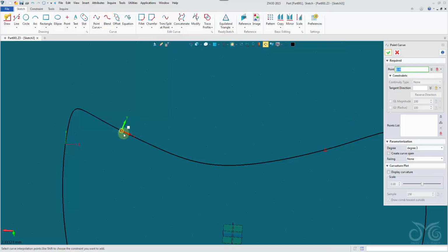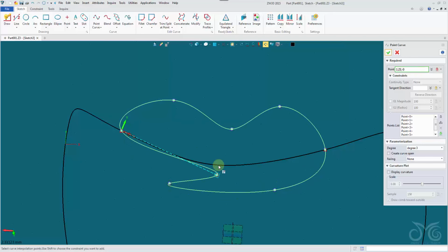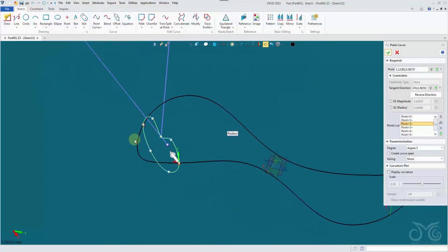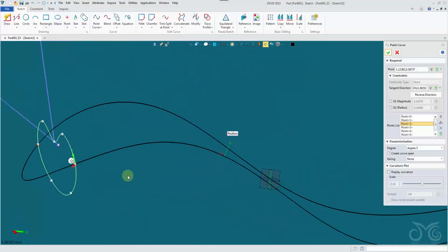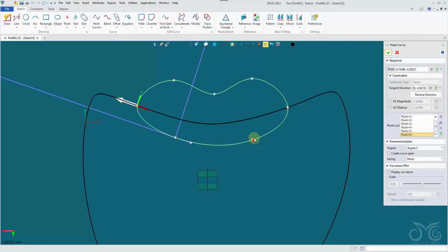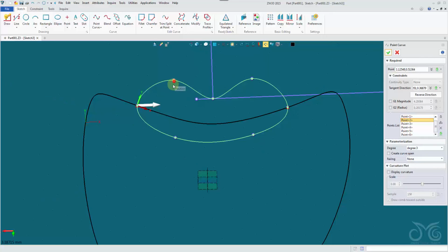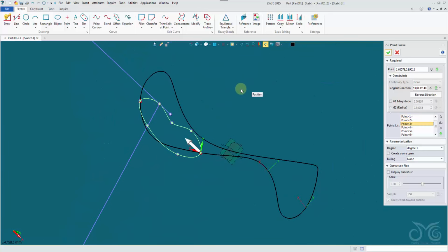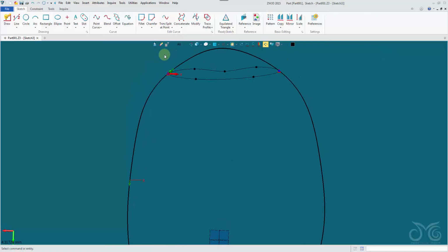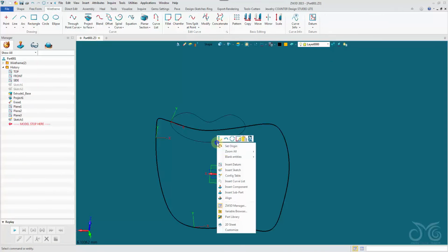create it closed. We start at our first intersection point. Just going to do this outline. We need to make sure we have another intersection, so let's snap in there. Okay, so I'm just doing something quickly. This will be building up our three-dimensional leaf. Okay, I'm going to confirm it. Exit back out into our part level and do the same for our other two datums.